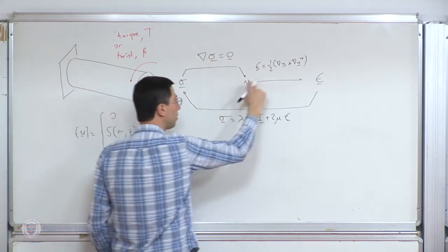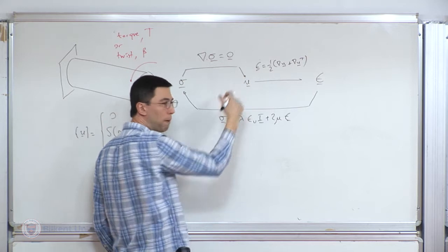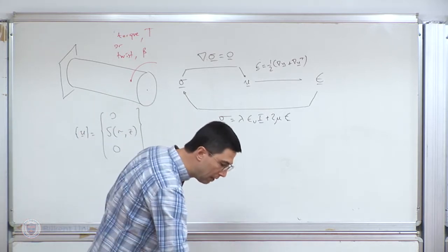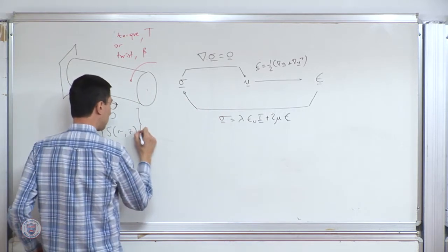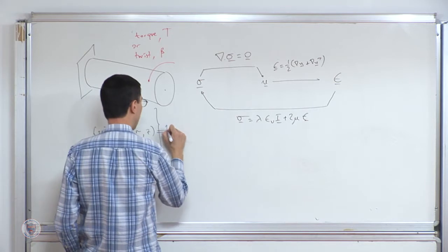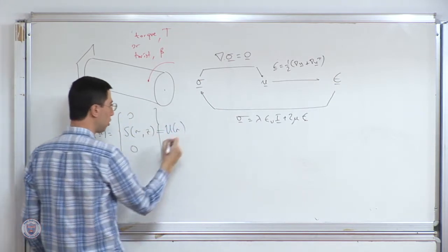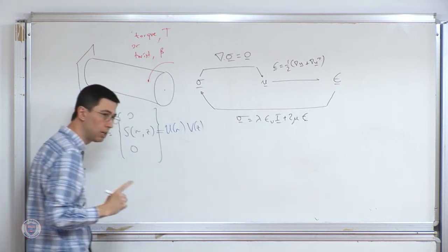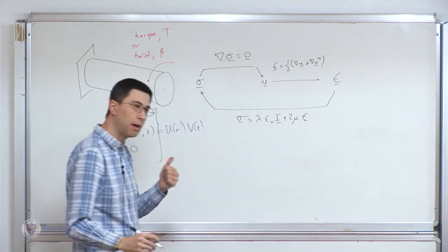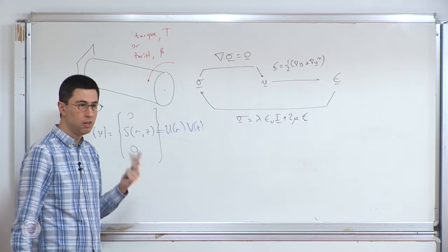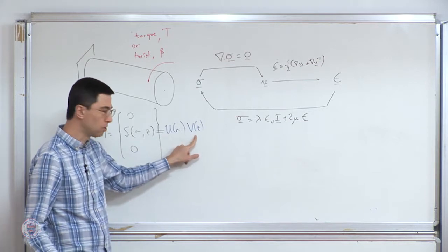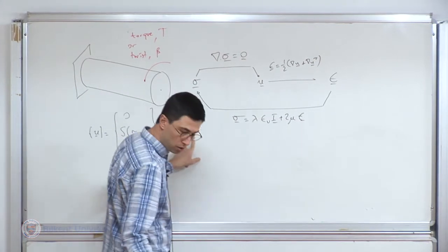Okay? So we plugged in, we came to that point, and we closed the loop, and we got a, let's say, a nasty equation because it was a PDE. And at that point, we said, well, let me follow a line of attack where I say that this U theta is represented through a separable solution. That is invoked by saying that it's a function of R alone times a function of Z alone. And then with that, we got two independent ordinary differential equations, both of them linear, both of them homogeneous, both of them second order, but the one for U was with non-constant coefficients, the one for V was constant coefficients. And that one was fairly easier to work with.